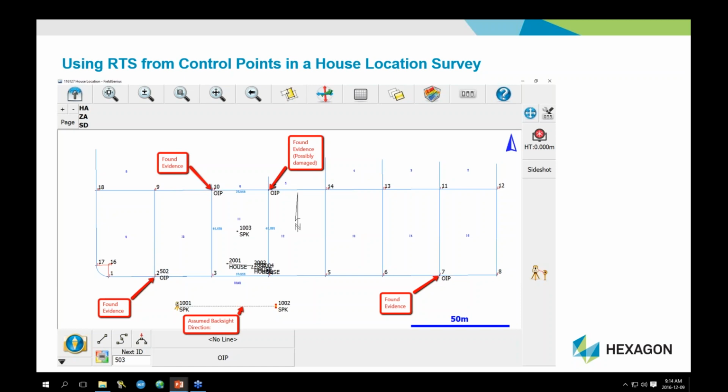You'll see in the center of the subject lot 11, 1003, that would be our second setup, and then the crew could tie the 2 iron posts they found at the back of the lot, or the north side. Now we can add those 2 things, redo the localization calculation, and confirm that all those pins match the plan information, and they'd be satisfied, and they could leave the job knowing that they don't have to go back to get more survey evidence, because what they found actually fits with the plan records.